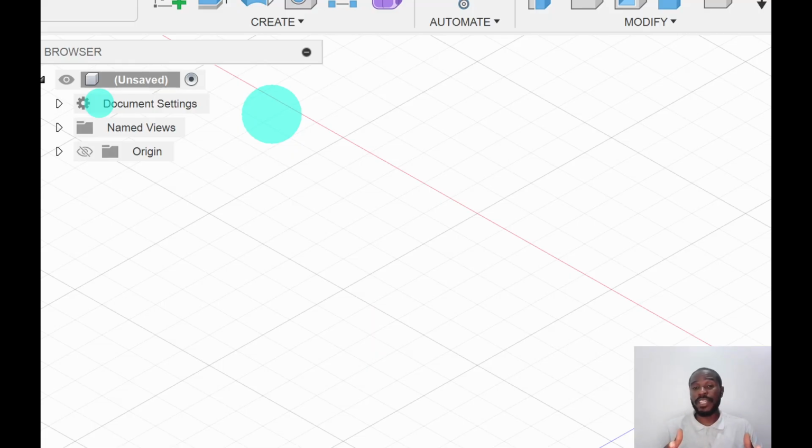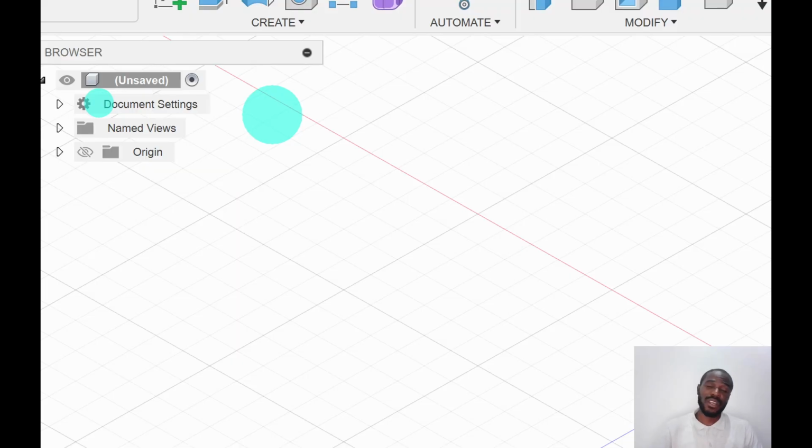In Fusion 360 and Inventor, when we click the metric system, we usually would work in millimeters. You can change all of those in the document settings there. And then you have the imperial or the English system of units that works in inches, in pounds, measures forces with pound force, and the rest.